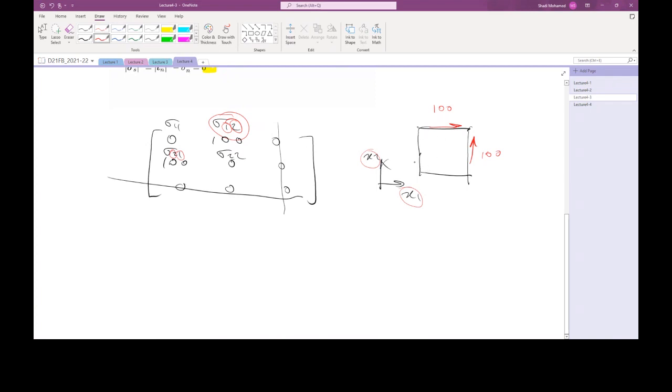Now, obviously for equilibrium, you need to have components active also on this plane and on this plane. So this is again 100 and 100, but this is active in the negative direction. This is double negative. If you look into the normal direction, this is opposite to x1. And if you look into the force itself, this is opposite to x2. So it is negative, negative, so it's going to cancel each other and it's going to be positive. All right, you agree with this?